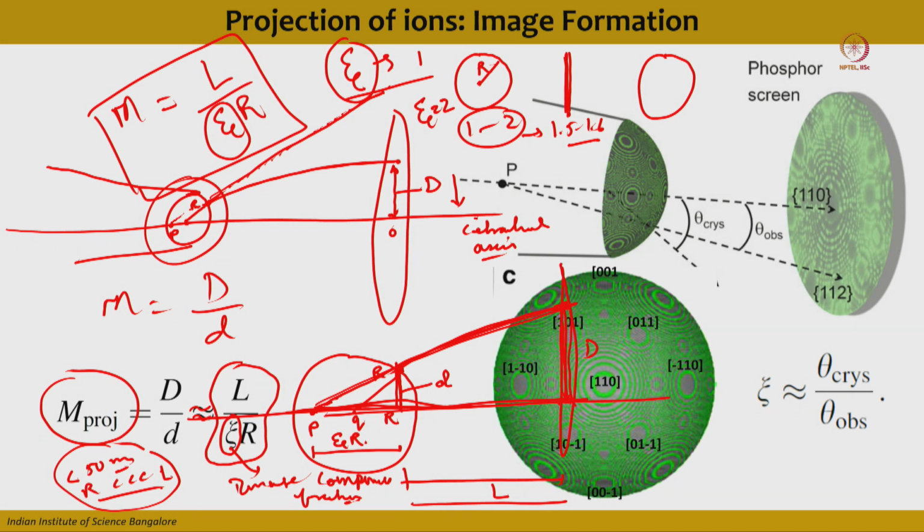How to calculate this phi? This can also be calculated crystallographically, because if your atom probe tip is crystallographically oriented in a particular direction, then whatever you are seeing on the field image is nothing but the image of the terraces of the atom probe tip. Here on the right side you can see an example of a BCC lattice of tungsten, and at the tip surface you have certain atomic terraces which are related to your crystallography. Fine.